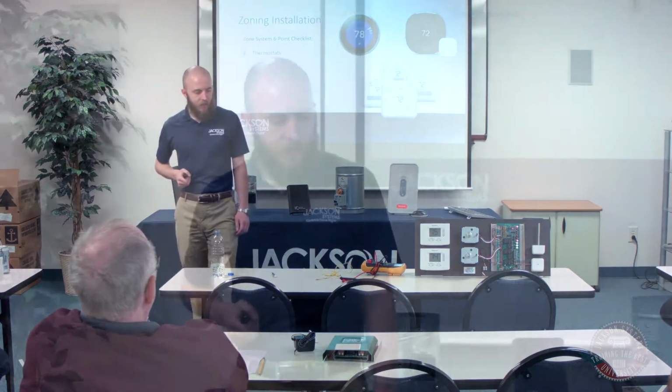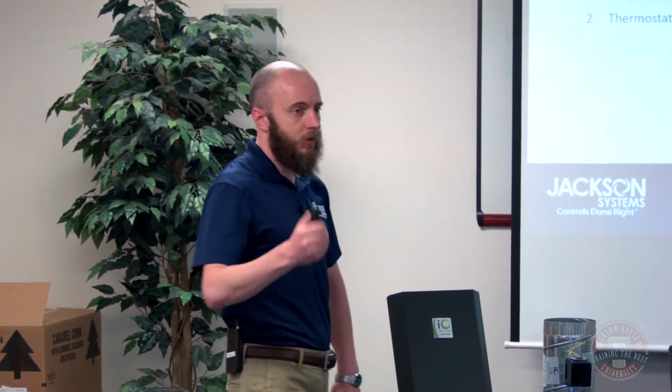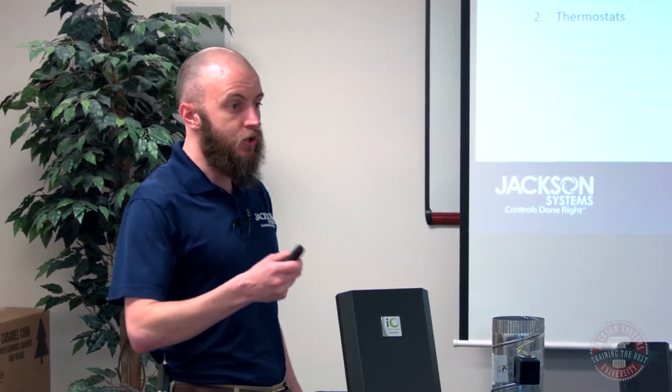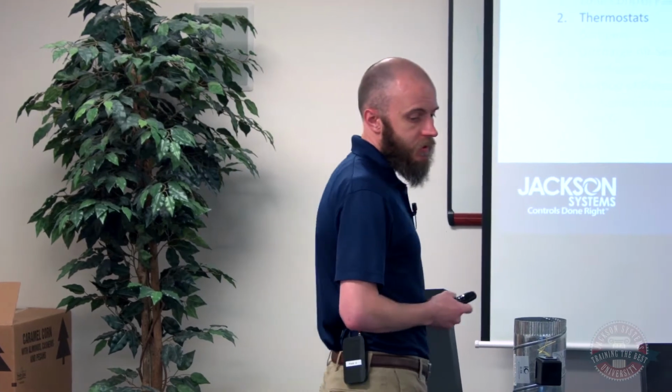Then you're going to need thermostats, obviously. So you're going to have a thermostat for each zone. You're going to sense the temperature in each zone and send calls for that zone so that each zone has its own temperature sensing.